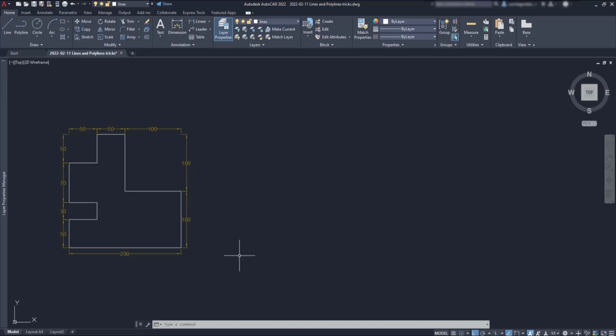Let's activate the command polyline. As you may know, I can click on the icon at the ribbon, or a faster way is using its alias. Just type PL and press Enter. Then I'm going to draw this irregular polygon, and let's make it beautifully, starting at the same horizontal plane. First, make sure Object Snap and Ortho Mode are on. The snaps are off. Let's turn them on. I'm going to hover this endpoint, drag to the right following this track line, and then I type 200 mm to start a polyline at that distance from the corner.